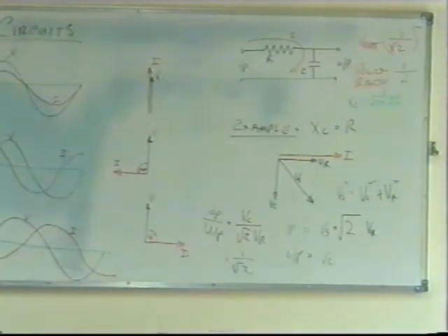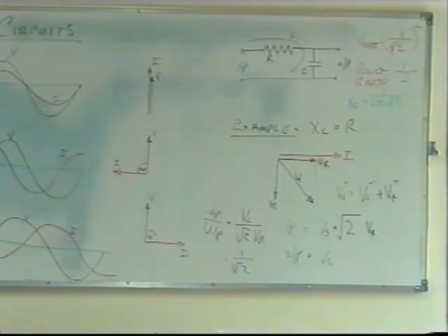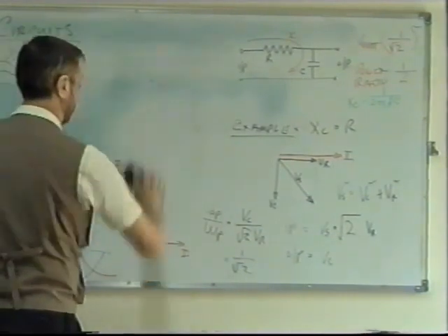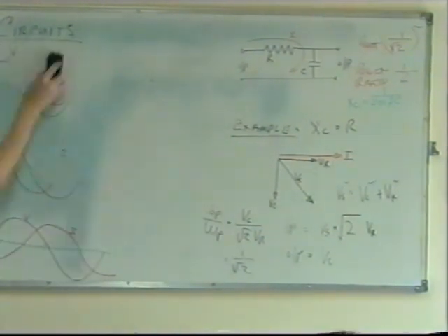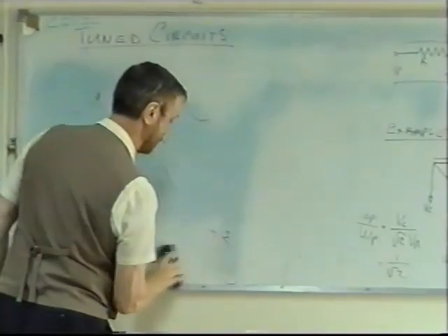And if you remember your decibels, in dBs, what does half power mean? Attenuation. It is attenuation, so it's a negative number. Remember, multiplied by 2, it's 3 dBs. So we're dividing by 2, minus 3 dBs. So we call that frequency the half power frequency, or the minus 3 dB frequency. Now let me just erase this and put the results of this on this side.